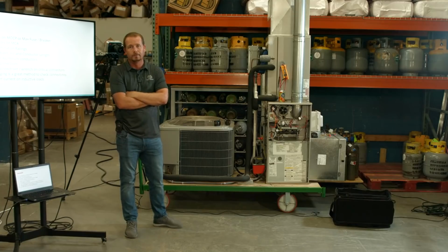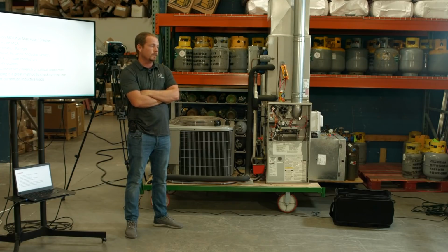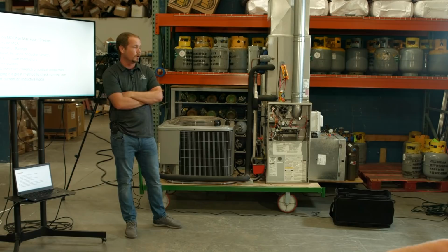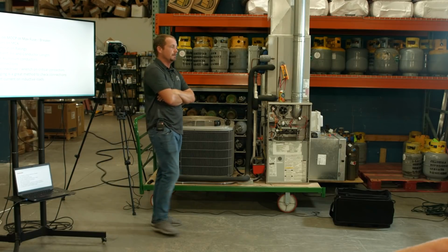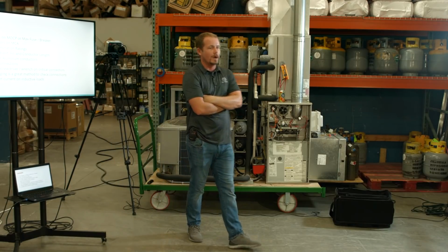I have an article about overload specifically. So if you go to the HVAC School app or to my site and just type in the word overload, there's an article specifically about this. Because really, the reason why we have these exceptions, that our breaker size doesn't have to protect our conductor, is because the overload in the compressor or the motors is protecting the conductor. So that's the reason why. And so understanding overload is really a key to that.